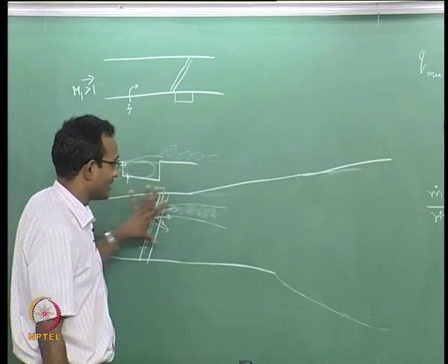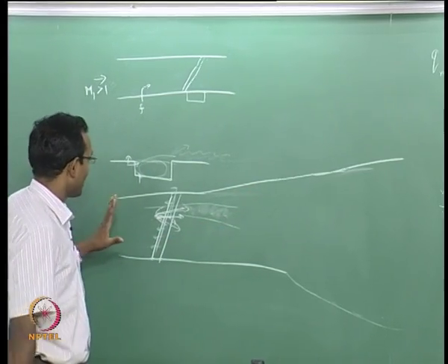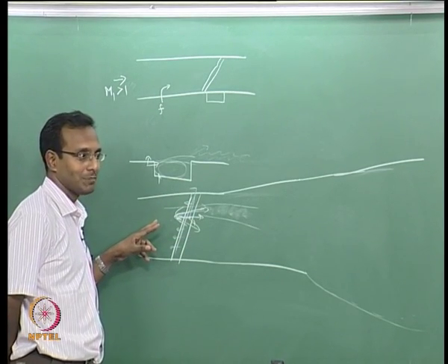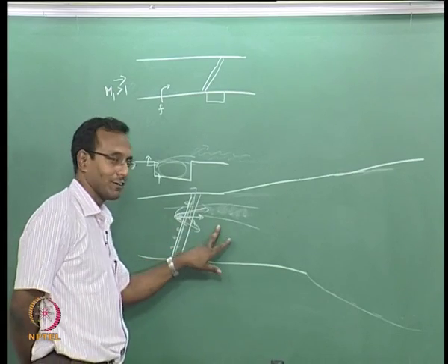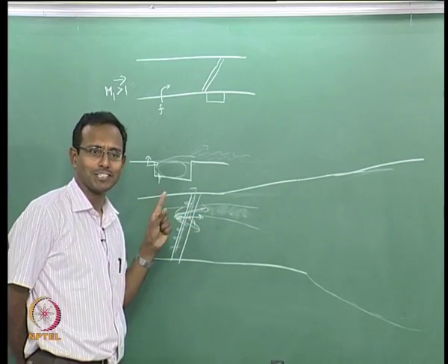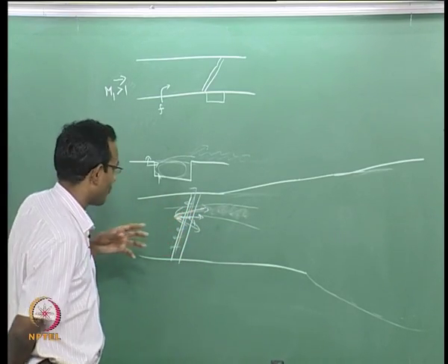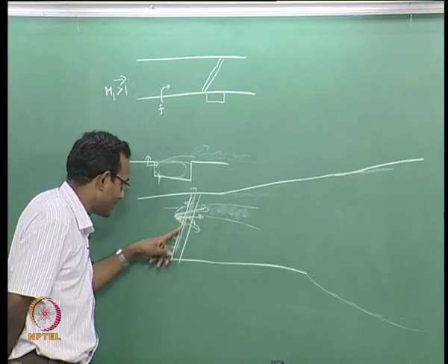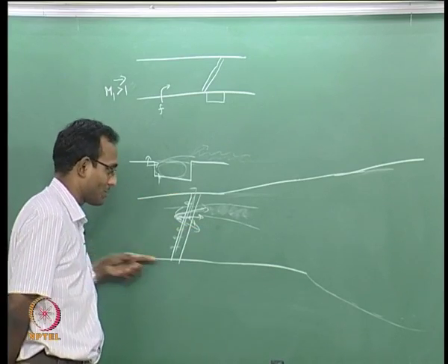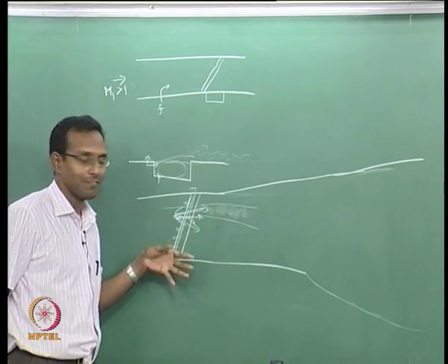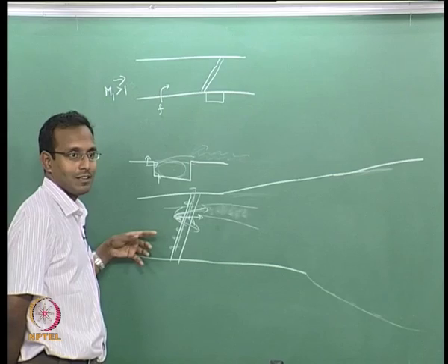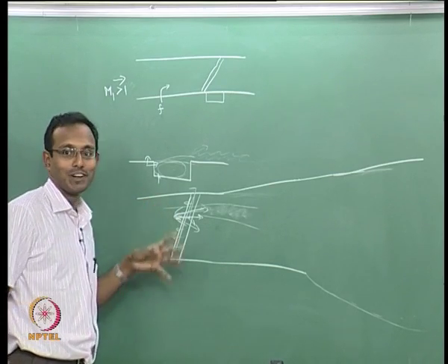So in this whole sequence I am starting with a supersonic flow, I added a lot of things which decreased my P naught, and I added heat finally, which took me closer to m equal to 1 by all these means. I did not talk about friction in this whole thing. Now if I think about friction also, there is friction on this rod, metal to the gas contact, or along the wall to the gas contact, friction is there everywhere, and that will also take it towards m equal to 1. That is why this whole problem becomes a little more tricky.